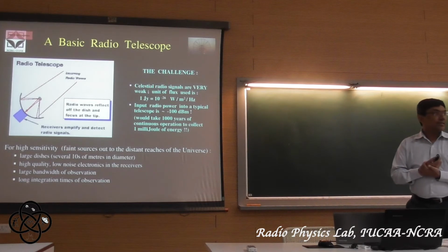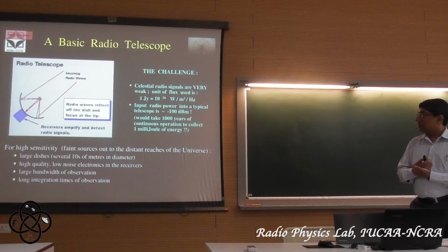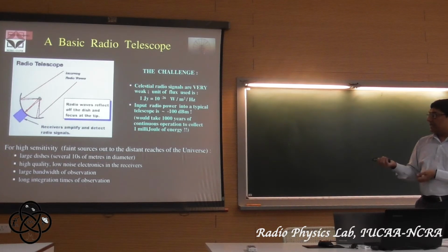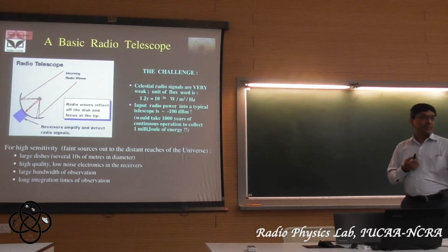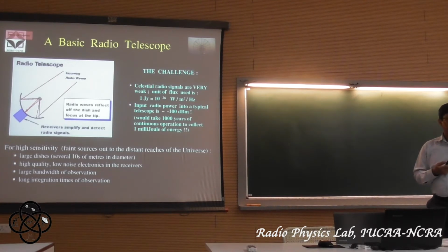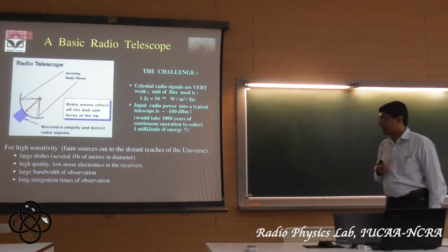In the case of a satellite dish, they're coming from the satellite in orbit around the Earth, and they bring the signal to a focus, either at the primary focus here, or in some cases the secondary focus, where the signal is further reflected. But finally, you pick up that signal in the sense that you convert the electromagnetic wave into a voltage, right, with a particular device which has the property. Again, as part of this detector technology that we were talking about.